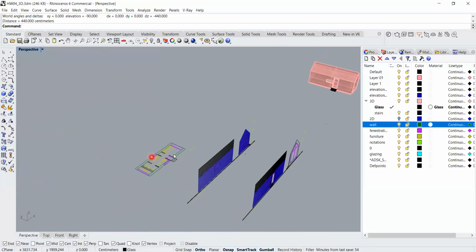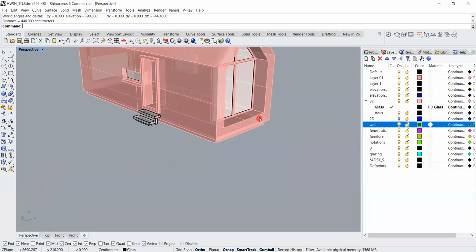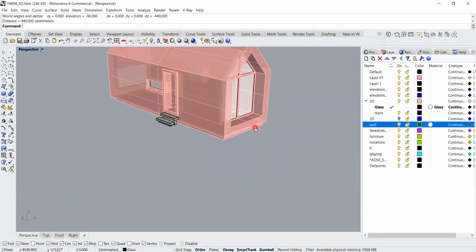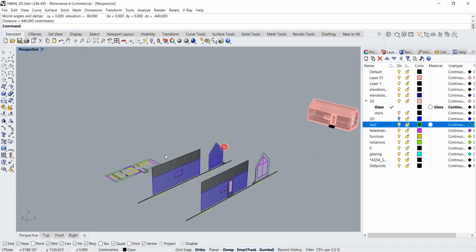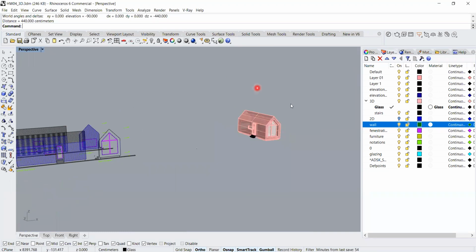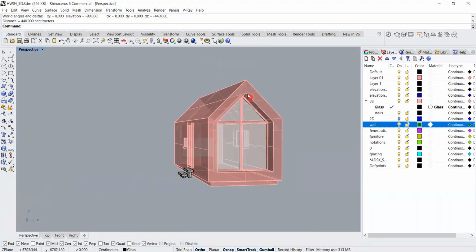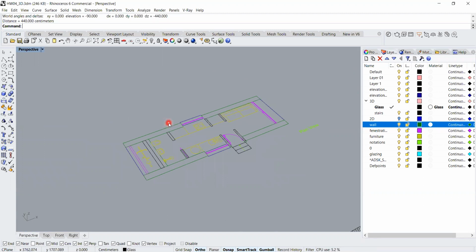this actually needs to be at least 440 centimeter. Of course, you have 40 centimeter for the slab here. So at least it needs to be 400 centimeter or 4 meter. Why? Because it needs to come out of these parts, so you can then trim them. Yeah. So let me just do it for you so you will understand it.